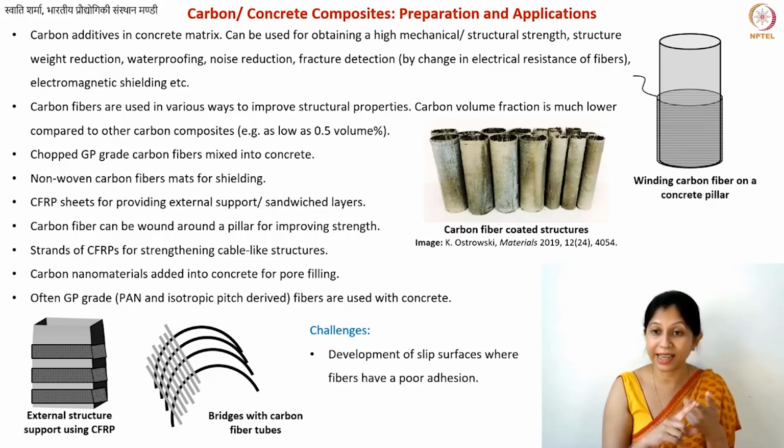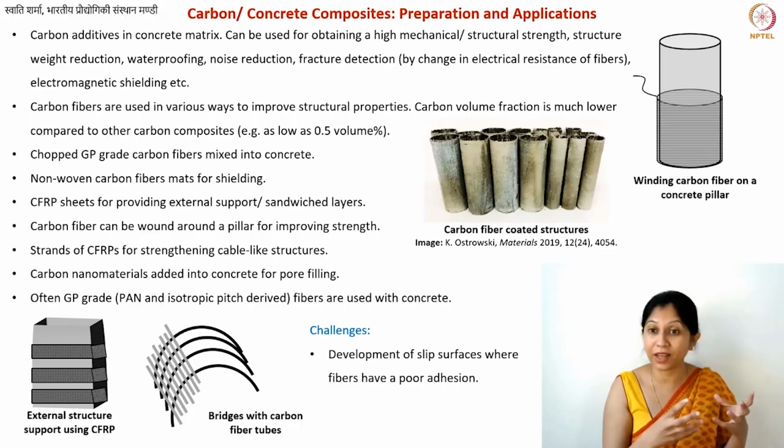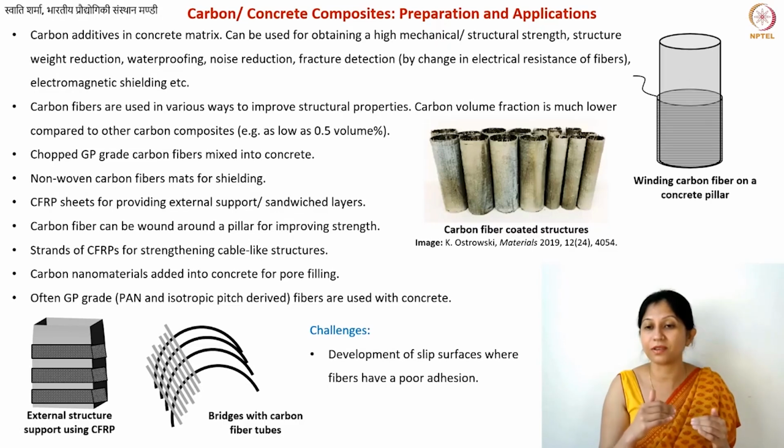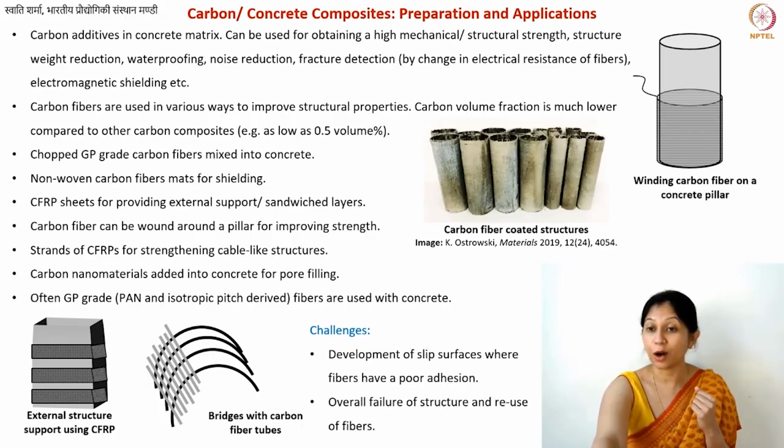So adhesion is important, yes, but you also need to understand the distribution of loads on your structure. Is your CFRP structure your load bearing structure? What happens if there is a certain crack in your structure? How much load can the CFRP bear, and where is the slip surface going to be? How is it going to break? So optimization of the mechanical performance and deformation is very important in the case of carbon reinforced concrete. Overall failure of the structure is something that you need to understand.